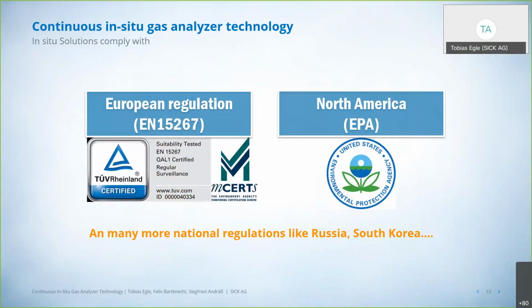Next. If you have to follow some kind of regulations, most analyzers are approved according to the European regulation by German TÜV or by Sira according to the MCERTs. And with the GPP probe, you have the availability to follow the US EPA.